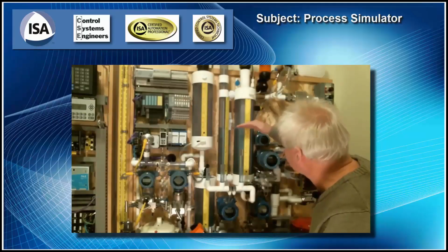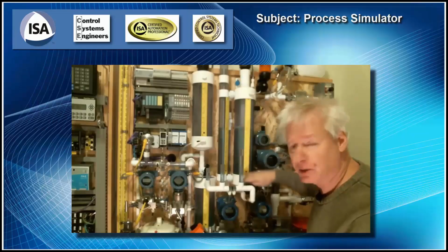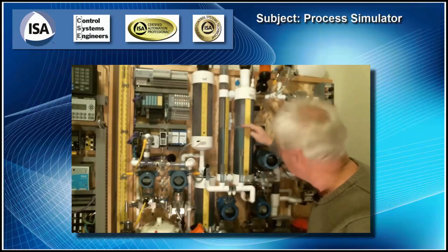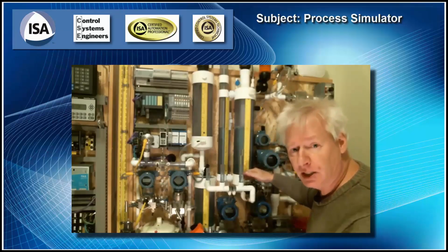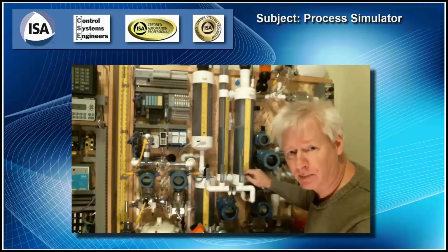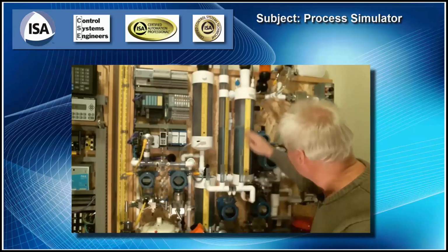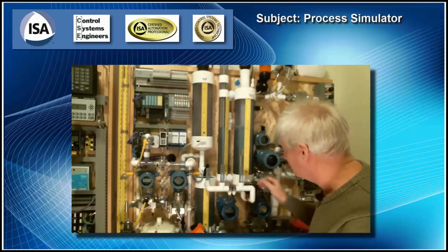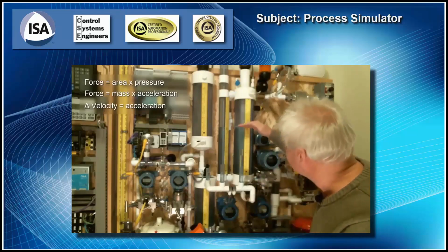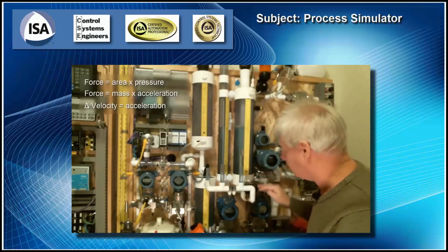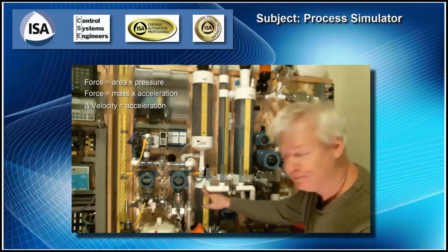Okay, so we've increased our height, which increased our energy storage. And by increasing the height, we've actually increased the weight of the water in here. Of course, weight is force. And force divided by area is pressure. This is what people like to talk about, pressure, but I want to get away from pressure and talk about head instead of pressure. By adding this weight and this force, we've taken the force, divided it by the mass, and we have acceleration. So this head of water is actually accelerating the water out of the tank and through the piping system.